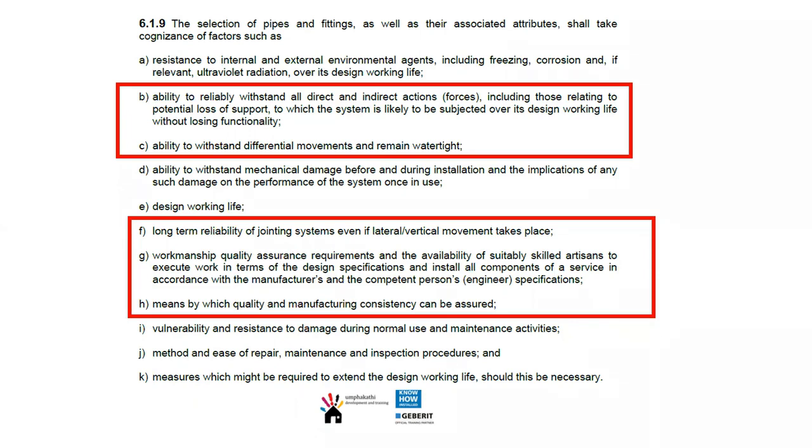And what we see quite a lot is that where contractors are putting in drainage and they've over-excavated 100 mil or 300 mil, and they put soft soil down and then they just lightly compact it or just rake it to the correct level. And obviously, as soon as that gets any sort of moisture in it, the fines are going to wash down and you're going to have a slight collapse. And that collapse doesn't need to be much. It can only be 50 mil, 100 mil, and then you'll have problems with your drain.